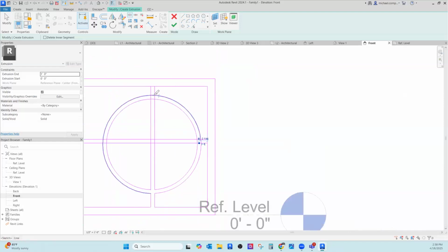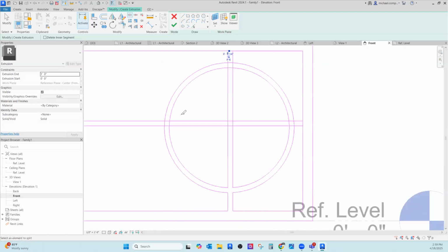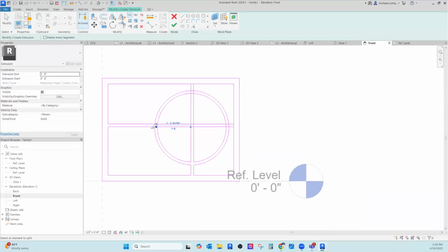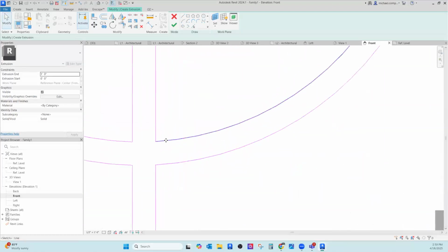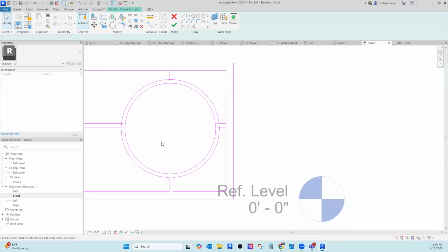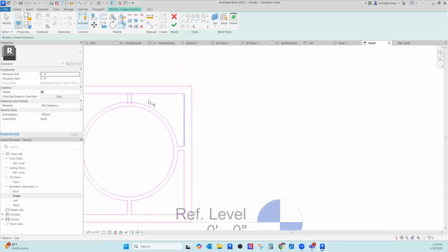I don't want the stuff in the middle. I just want the stuff on the ends. So we'll do that in a second. Sometimes it's easier just to stay within the tool. So I'm using the cut tool, and then I'll go back and trim everything. I've changed my mind as a designer. I don't want these pieces. I'm going to delete them. I don't want those pieces anymore. So now I just want the edges. So using the trim tool, which is my favorite, I'm going to cut these things.